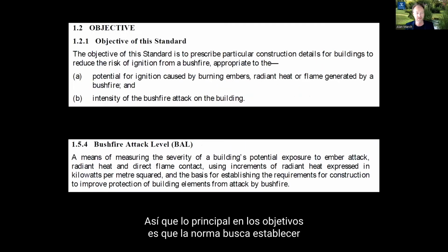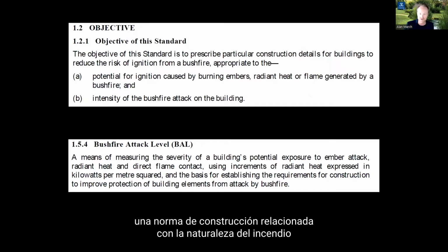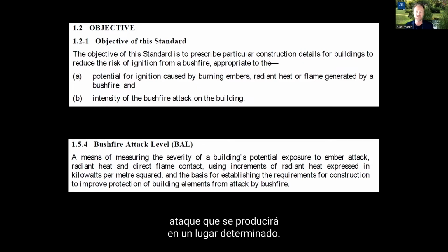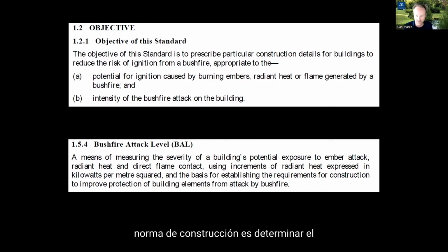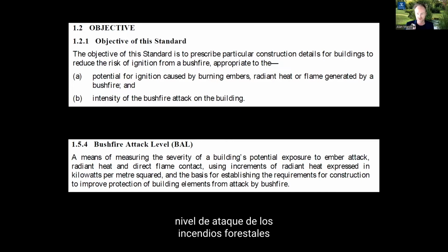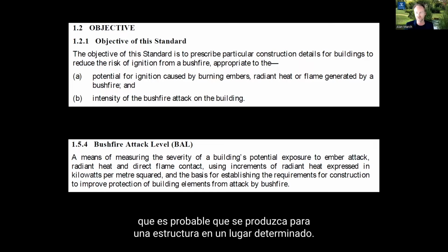So the main thing in the objectives is that the standard seeks to establish a construction standard that relates to the nature of the fire attack that will occur in a particular location. And a cornerstone of this establishment of the appropriate construction standard is determining the bushfire attack level that is likely to occur for a structure in a particular location.